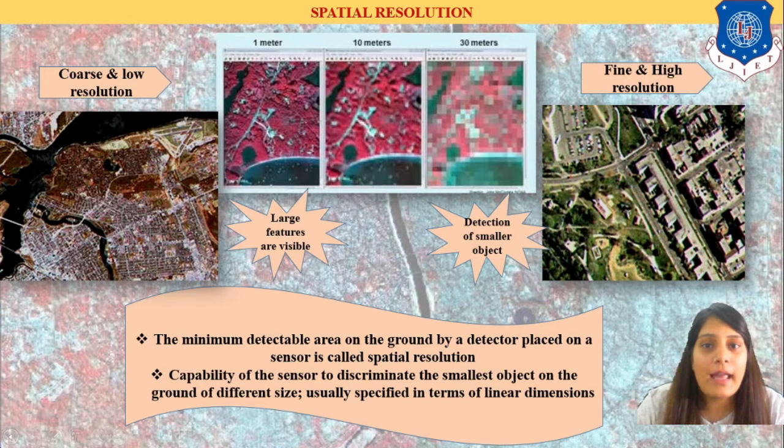You can see here I have shown the image which is taken from the sensor for 1 meter, 10 meter and 30 meter. You can see here in 1 meter more area is covered, but you cannot properly demarcate the feature. Yes, you can demarcate the feature, but more area is covered. Similarly, looking at 10 meter and 30 meter, 30 meter is so zoomed in that we cannot get the proper information. But yes, you can see here that we can get the pixel intensity very properly in this. As you can see here, the various pixels are shown.